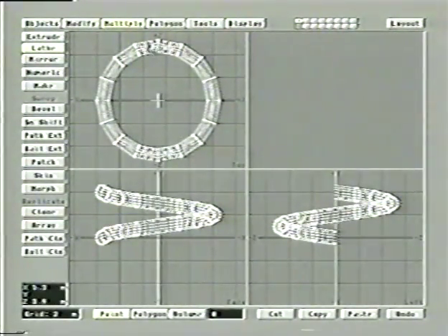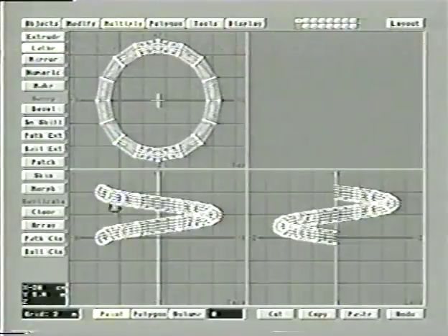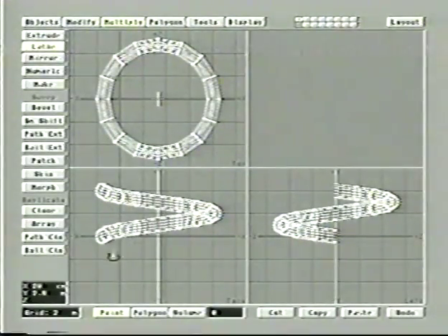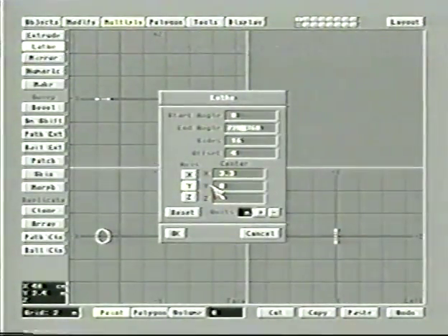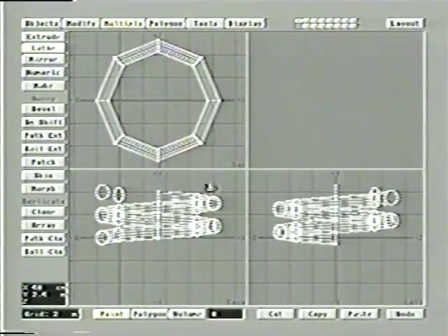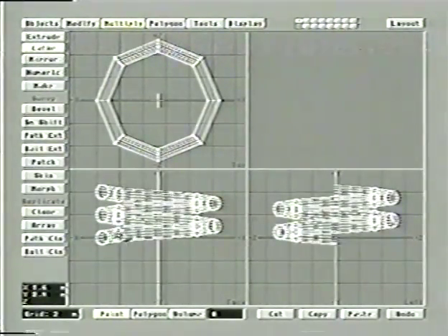And from the top here, it looks pretty much the same. It's doing 360. But from the sides, of course, you can see it's not only spinning it around, it's raising it. Now, this is where it can be handy to add more degrees for our end angle. If we set it to 720 degrees now, it's going to sweep it around this way twice as it raises it up. So let's undo that. Numerically change end angle to 720. And so now it's spinning it around a couple times.